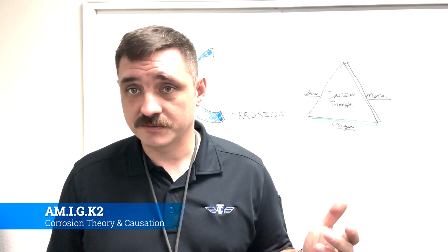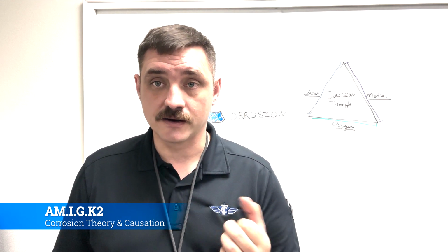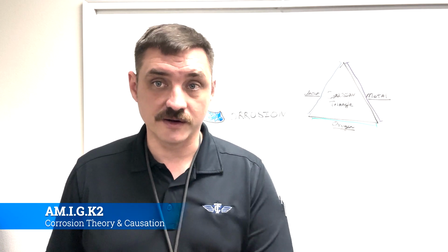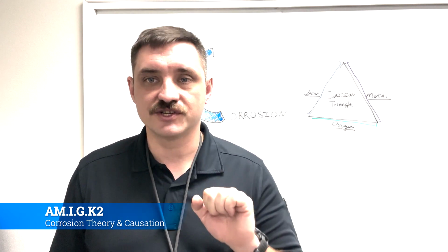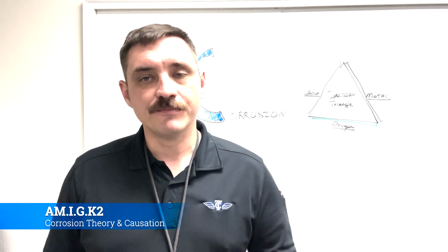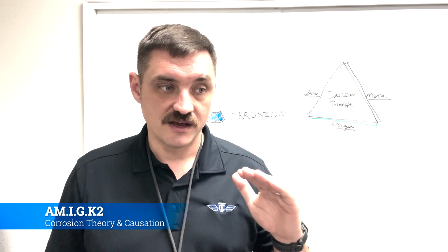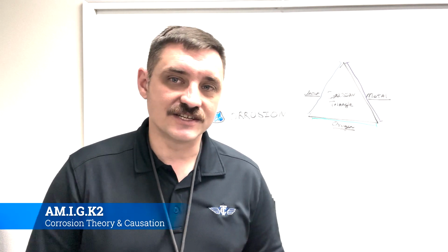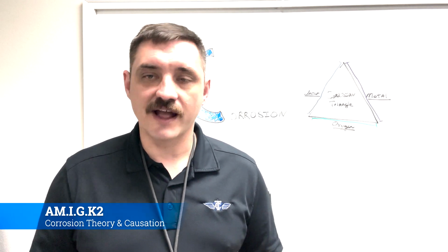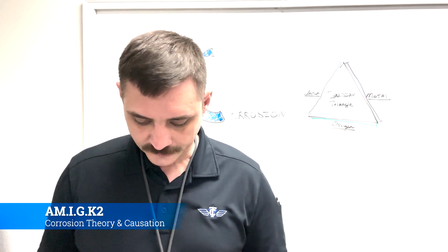So earlier we talked about my experience with the 58 and the tail rotor gearbox having that little plate right there. That plate was also very susceptible to corrosion. That whole area was, and the reason being is the strain that's constantly being put on it, stretching the metal and creating new areas. So you have to reapply paint on a pretty regular basis, because as it starts to stretch, the surface of the paint starts to crack. As it starts to crack, it allows things to come in there and that can get corrosion going.